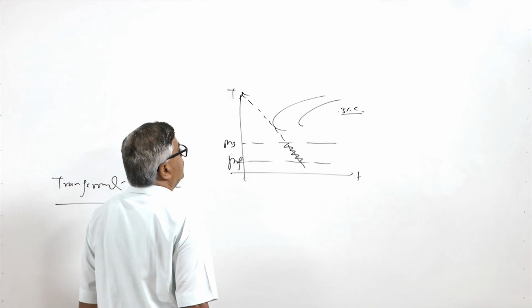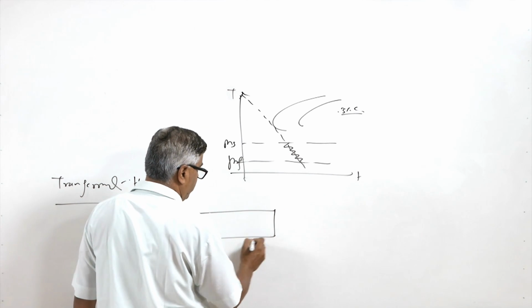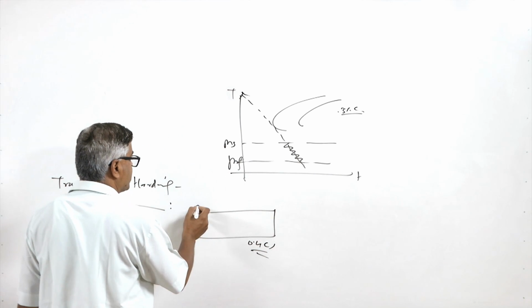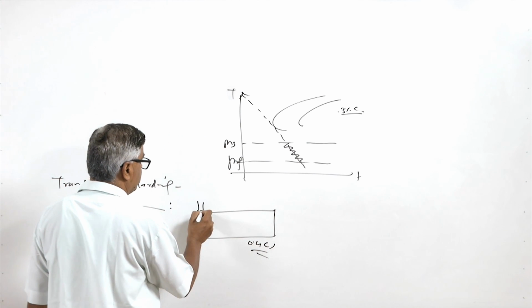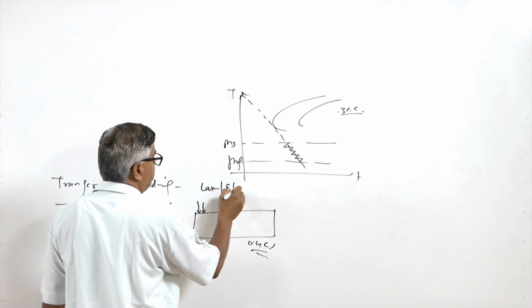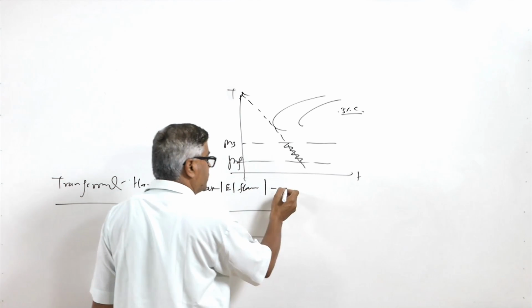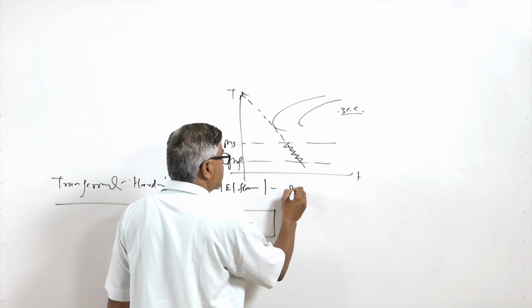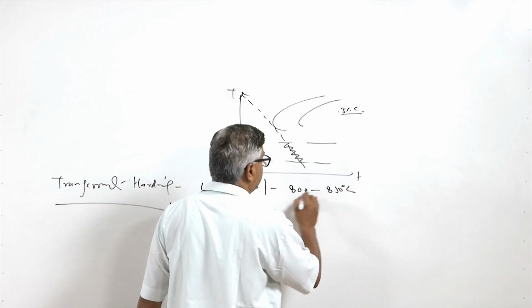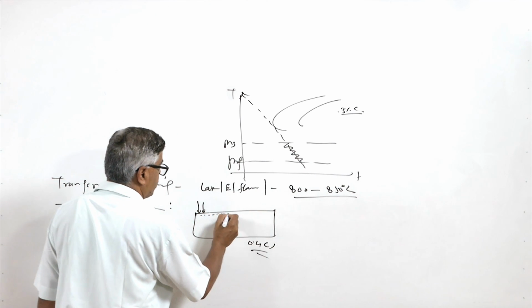And this is the austenitic zone. The component, say 0.4% carbon steel, has its surface heated through a suitable source of heat like laser, electron beam or flame. Heating is done in such a way that it gets heated above 800 to 850 degrees centigrade, so homogeneous austenite near the surface layers is formed.